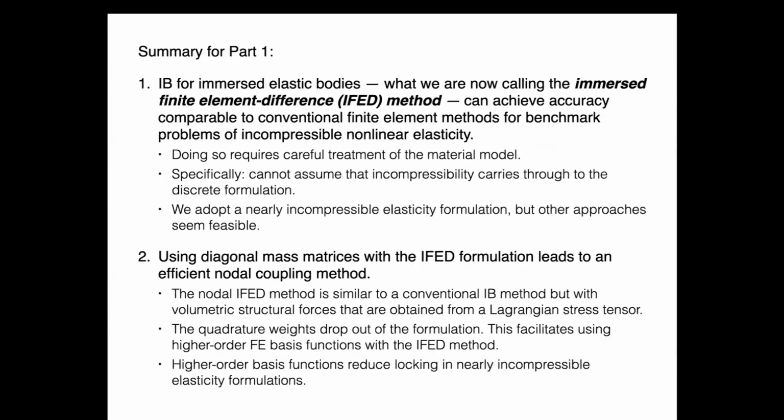All right, so we've got a framework that lets us use immersed boundary type methods to do pretty complicated sorts of constituent models for hyperelastic, nonlinear material models. There's not really any restriction to hyperelasticity. Anything you can describe with a stress tensor and some state variables you can in principle use.